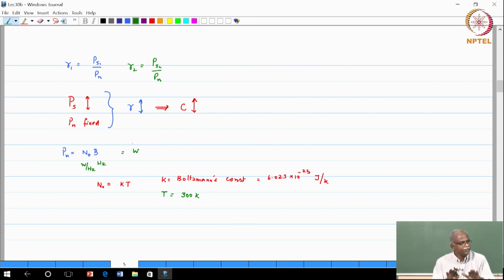Okay. So, I am sure you have done this calculation and you are familiar with it. So, the problem is, actually I want watts per hertz. Basically K times T will give me joules, and joules per second is equal to watts. So, if I write joules as watt seconds, this can be written as watts per hertz. Everything is clean. Basically, K times T gives you a quantity which is in watts per hertz, and you multiply it by the bandwidth, you will get watts.